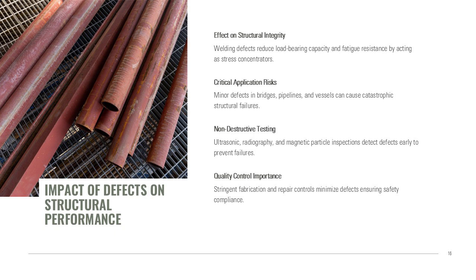Welding defects significantly reduce the load-bearing capacity and fatigue resistance of steel structures. Defects act as stress concentrators, accelerating crack initiation and propagation under cyclic loads. In critical applications such as bridges, pipelines, and pressure vessels, even minor defects can lead to catastrophic failures.